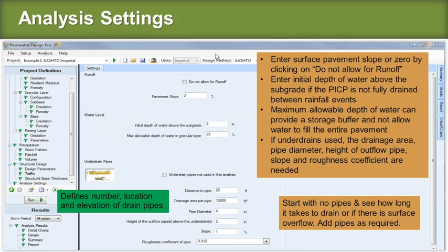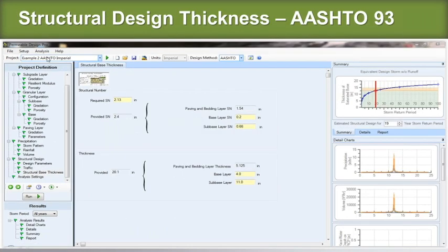So again, it's an incredibly powerful tool to do partial infiltration designs. A lot of what ifs. I spent a lot of time with the pipes: how big they are, how many you need, what spacing they need, how high they need to be above the subgrade, and things like that. So, lots of this kind of stuff.